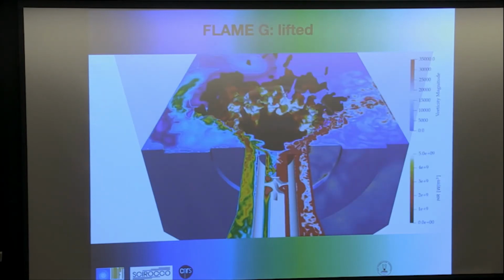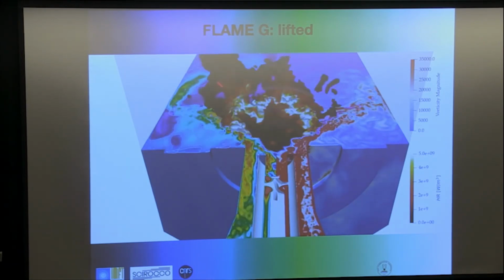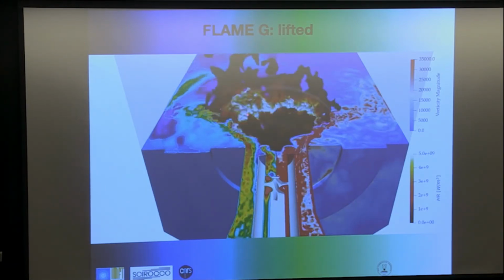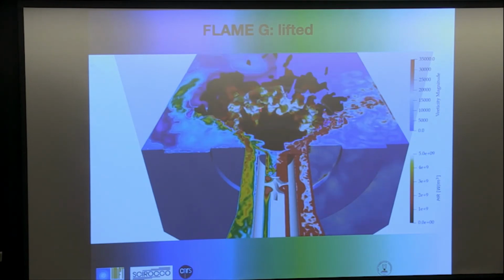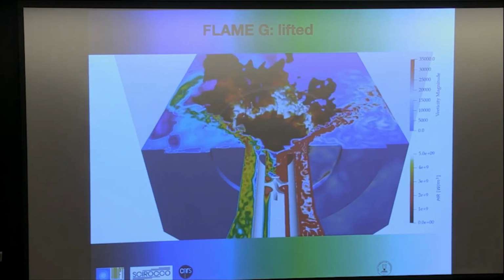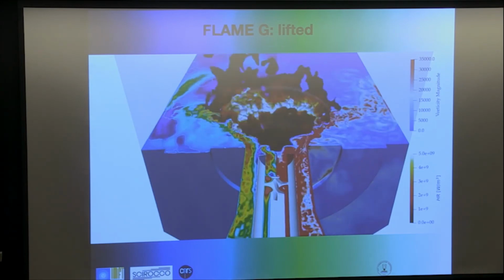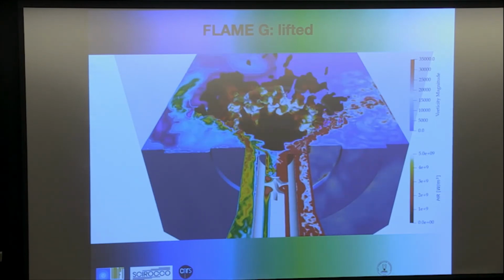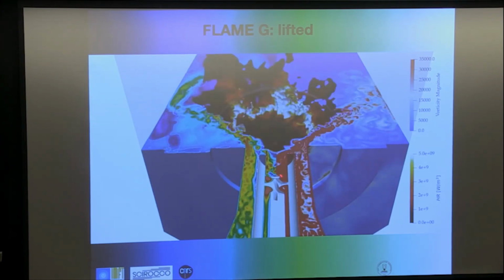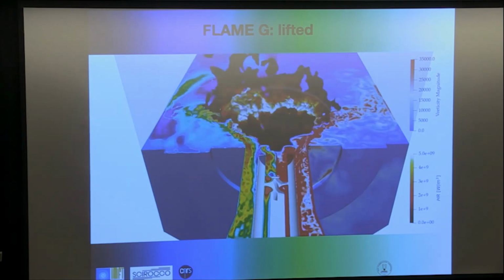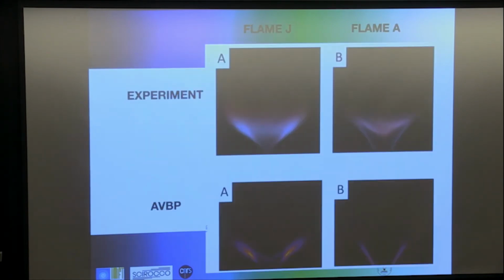While if you go to a lifted flame, you see now for this case, LES actually shows that the flame is not anchored to the lips anymore. The flame is sitting somewhere here. And if you look at its characteristic, you see it's a premixed flame. It makes much less NOx. And the lips here of the injector are much cooler, which is, of course, better for the lifetime.